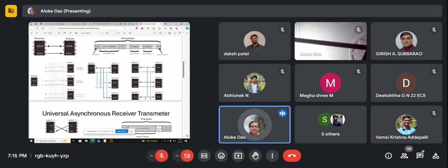Basically, there is a ternary operator: question mark, colon. The control signal should be first, then the question mark, then the input signal. Then after the colon, you have to write the high impedance value, like 8'hZZ.